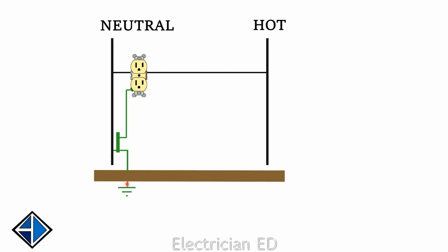Okay. Here, this represents a ground rod. This would be your grounding electrode conductor. This is a ground bar that would be inside a main panel. It wouldn't just be floating around. You wouldn't be doing this on every branch circuit or every outlet.